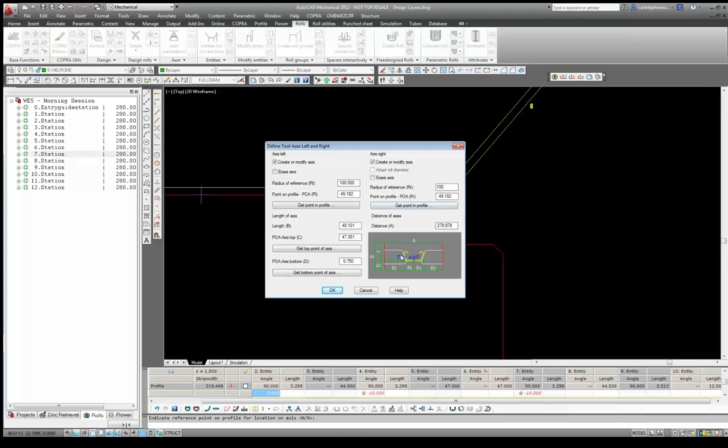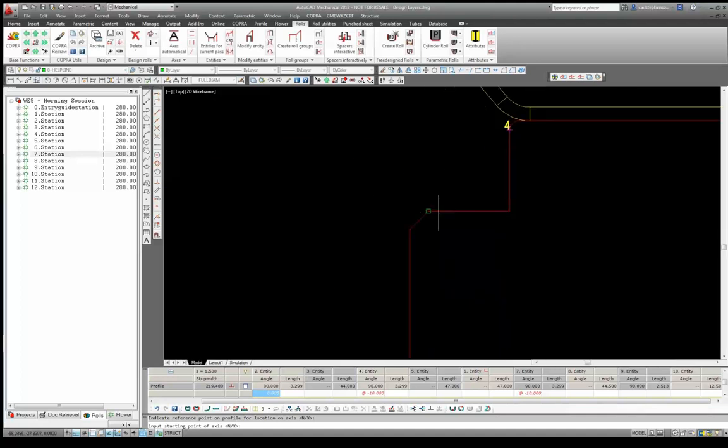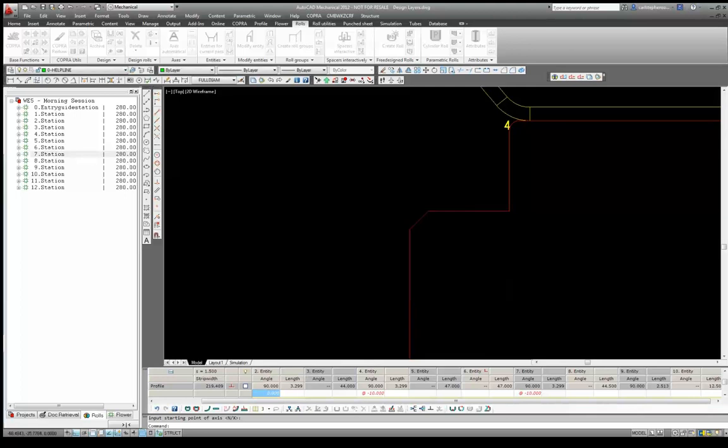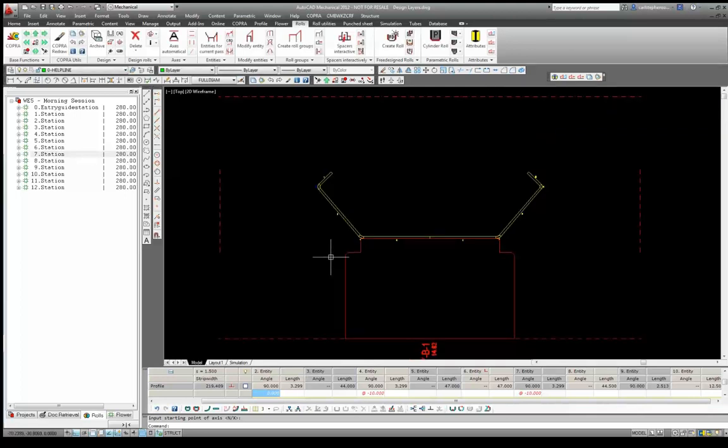Now the bottom point of the axis for me in this will be the shoulder I created on the bottom roll, which we can see is here. And in the length of my side roll axis, I want to make a nice round number of 60 millimeters. A description of each of these parameters is shown here graphically in the window. So of course you can manipulate these without actually returning to the AutoCAD window. Now press OK. And we can see our axes are updated.